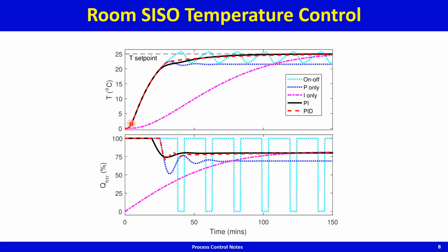In response, temperature rises as before, and as the temperature approaches set point closely, the heater duty starts decreasing and the temperature oscillates a little bit and settles. But then you see there is this offset. The final value at which the temperature settles is not 25 degrees Celsius, it's maybe 21 or 22 degrees Celsius. So there is this offset with proportional control.